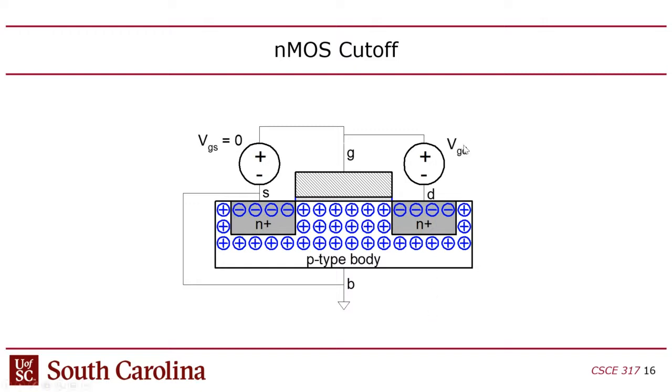So you've got the nMOS in cutoff mode, and basically the voltage in this case from gate to source is 0. And I mentioned that with the nMOS, you're typically going to have, well, not always, these sources and drains, when you build the pull down network, close to grounded anyway. So the voltage of the gate is going to be 0.